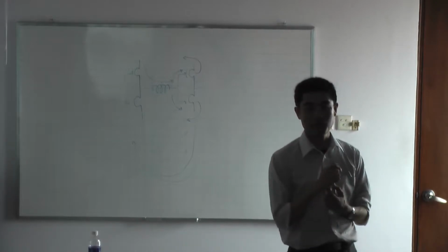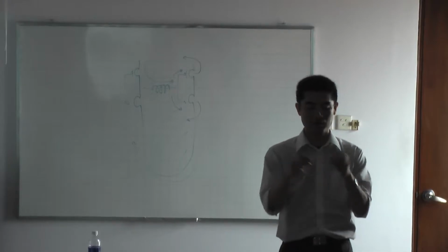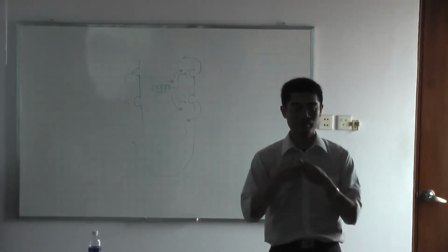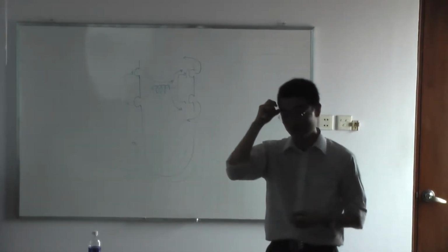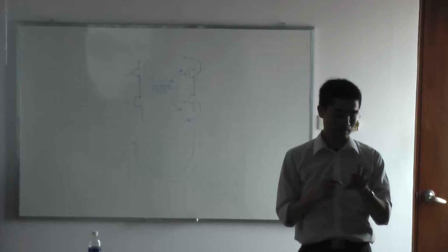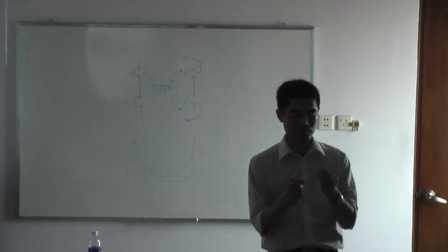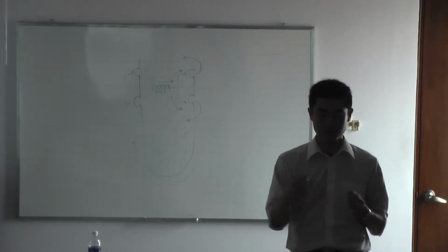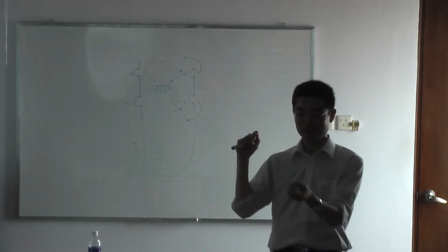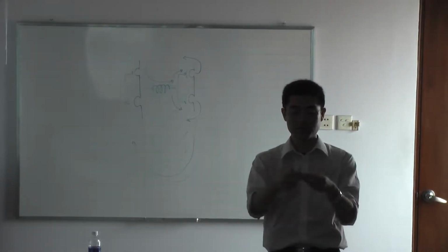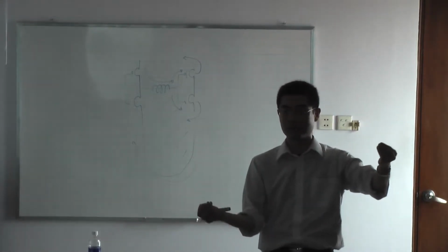And also we will have power splitters that will split the input signal into two parts. We often use this for measurements. For example, we sometimes want to see the waveform on the oscilloscope and on the spectrum analyzer at the same time. At that time, the output is input to the divider, and one of the outputs goes to the oscilloscope, and one of the outputs goes to the spectrum analyzer.